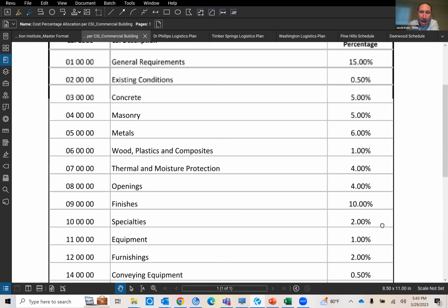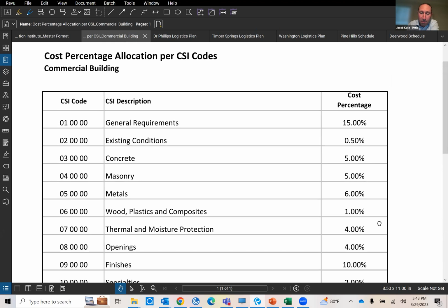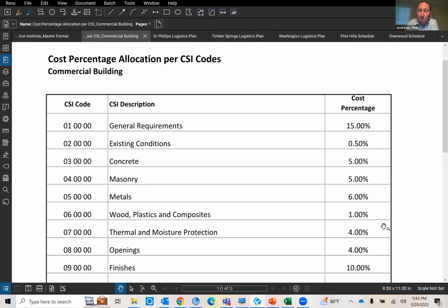So that is, generally speaking, what we want every team to do for estimating your projects. I'm just going to summarize real quick. You need to identify the area of your project in square footage. You need to apply either $400 per square foot against that square footage, or establish what cost per square foot you are going to use and explain why.